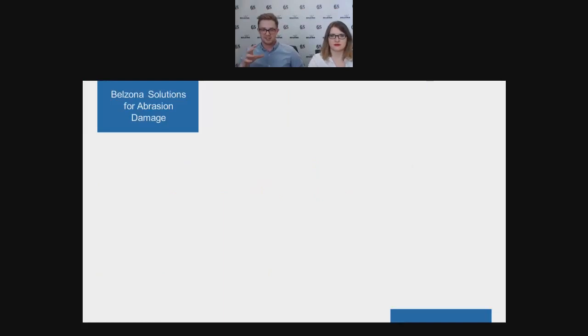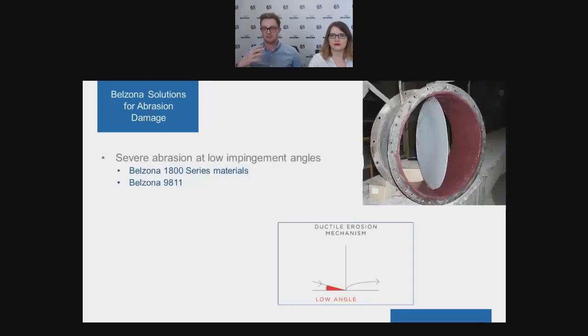So if we want to select the right material for this type of application, this is always influenced by this angle of incidence. So for angles under the 30-degree limit, the threshold, the harder materials usually perform much better. So epoxy coatings, whereas the elastomeric materials tend to cut and tear more readily. So they get increased wear rates, whereas the epoxy materials get lower wear rates.